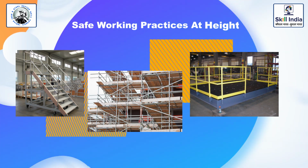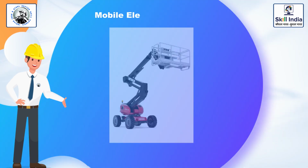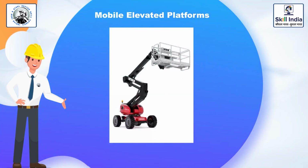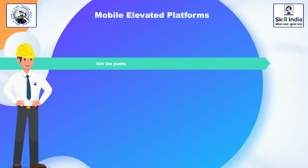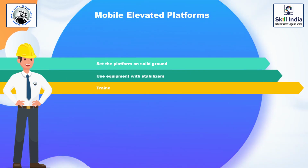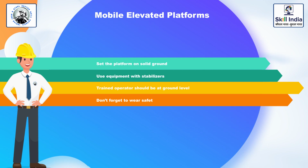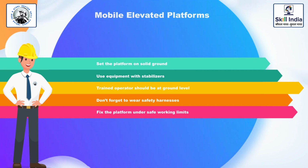Let us look at some of the safe working practices at height. If you are using mobile elevated platforms as shown on your screen, you need to set the platform on plain and solid ground, use equipment with stabilizers, trained operators should be at ground level. While working on platforms, don't forget to wear safety harnesses. Fix the platform under safe working limits and keep an eye on the speed of the wind.